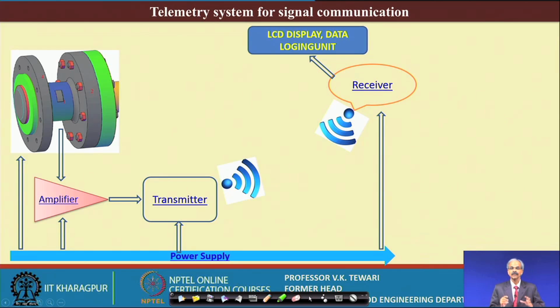Well, the telemetry system, as I told you, we have designed this system, and we are measuring using radio frequency, so that we do not have to touch anything. And although this instrument has the strain gauges, they are put in such a way that we are in a position to record the data wirelessly, and this is the beauty of this.